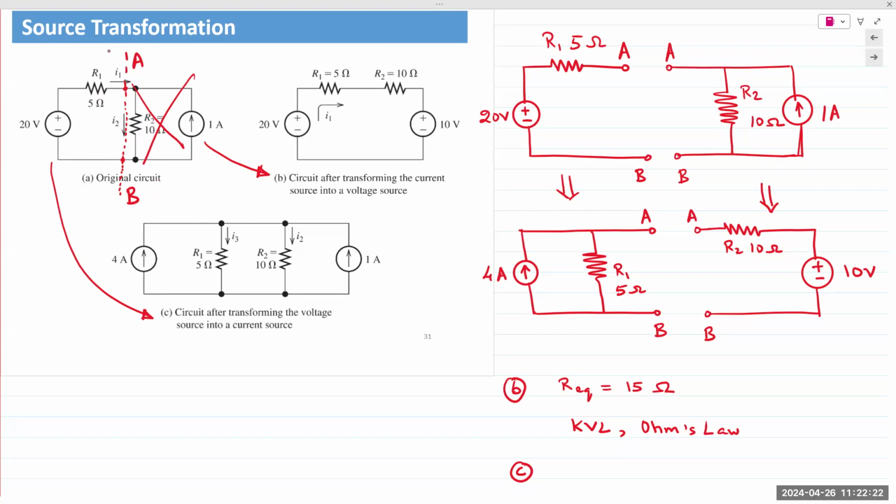So I took that apart. And if I was considering the Norton, which is on the other side, the only thing I care about is it should have a resistor in parallel with that current source, because that would give me a Norton circuit. And then what is on the other side, I don't really care. And so that's the point where I would disconnect it. Make sense? Okay. In this case, of course, the circuit is chosen such that it breaks up exactly in equal parts. But a large circuit could have multiple different components in the middle.